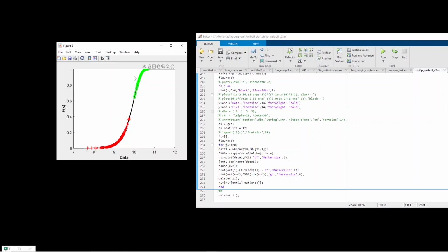If we want to calculate, for example, a 5% confidence band, then instead of calculating the median, we calculate the 5%. So with 5% chance, basically everything will be here. With 95%, we come to somewhere here. And basically we calculate the probability of failure for 5% and the probability of failure for 95%, and we assign that to the first sample. The same way we do for all samples. And from there, we can calculate the confidence band of 5% or the confidence band of 95%.